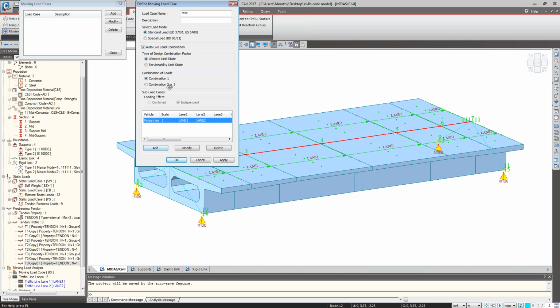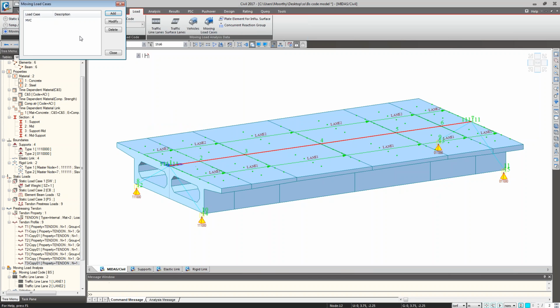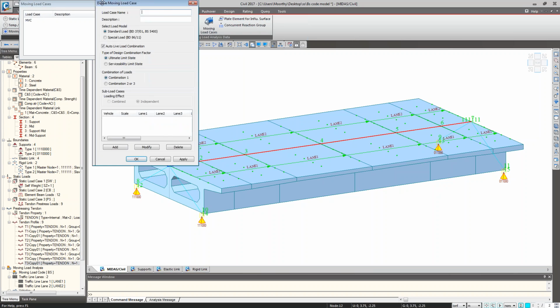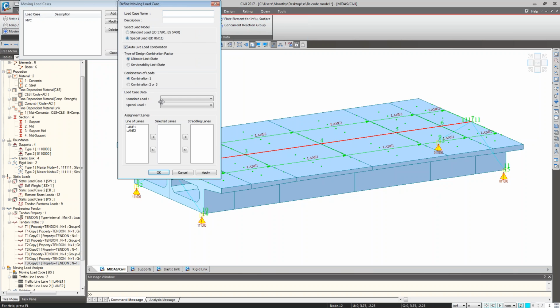Again, this is added. Again, second for the live load case. HA loading for both the lanes occupied. This is another critical condition. The first one is for the pedestrian case, second is for the live load. This is for the load case MVC underscore HA loading.